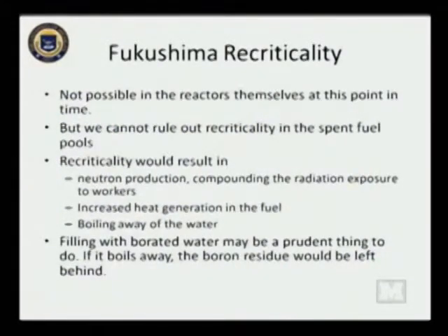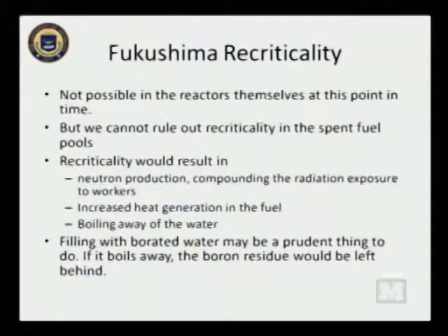So filling with borated water may be a prudent thing to do. If it boils away, at least the boron's left behind. So they may be using borated water. I don't know. If they are, that's the prudent thing. They did use borated seawater that was injected into reactors 1, 2, and 3. That's the prudent thing to do. I think a recriticality is highly unlikely. There are some strange, narrow circumstances where you can say, well, this is possible. They just simply remove that by being prudent and adding boron to the water. So I'm guessing that this is well thought out, or people are thinking about it, and they'll do the prudent thing if they can.